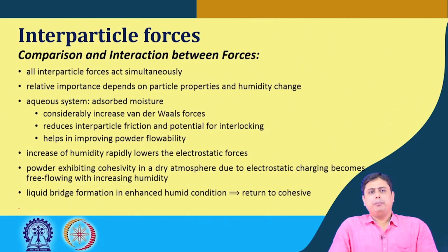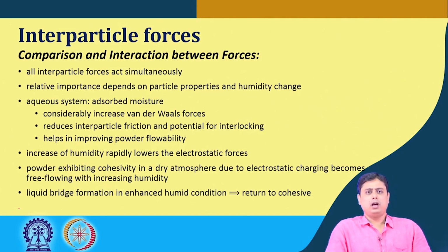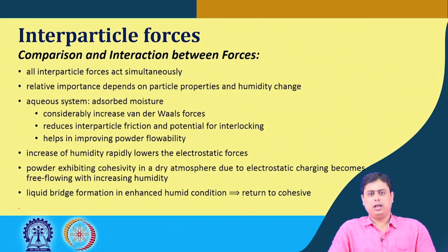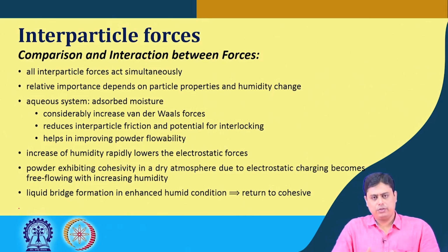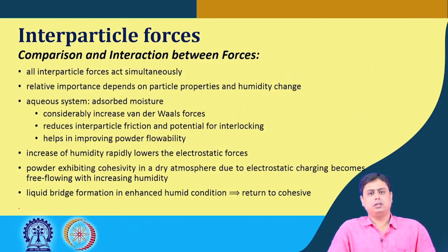So, if we compare the relative strength of these forces, or which one is dominant, we see that all interparticle forces are acting simultaneously, and their relative importance depends on the particle property and the surrounding humidity, the operating atmosphere. So, for example, for any aqueous system, the absorbed moisture can considerably increase the van der Waals forces. If the surrounding atmosphere contains sufficient moisture, then it can reduce the interparticle friction and the potential for interlocking, which is not helpful.